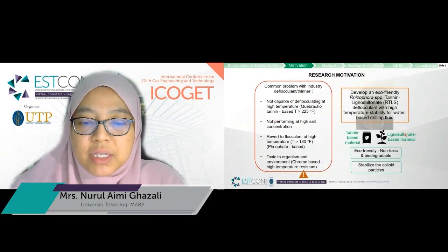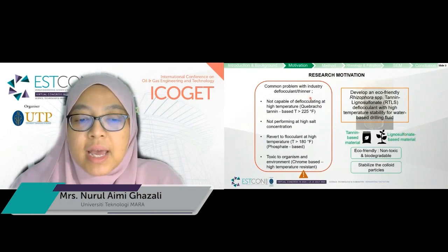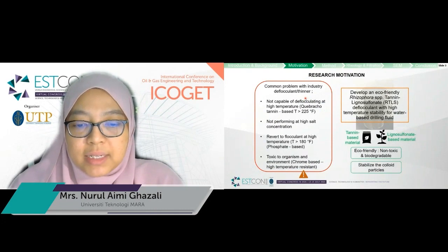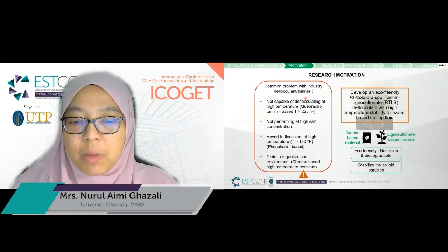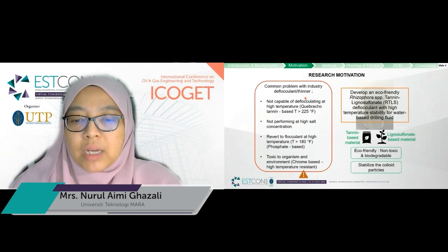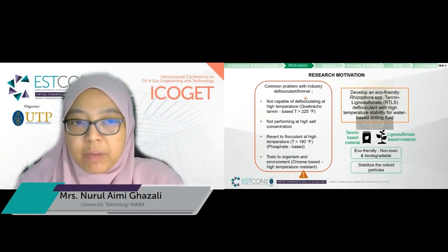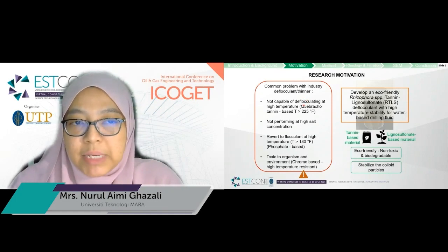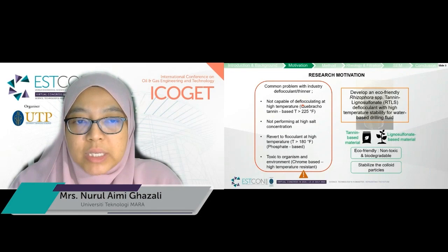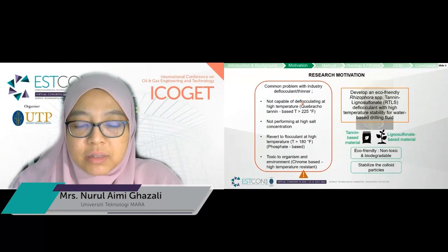In past research, lignosulfonate was introduced to replace quebracho tannin as the deflocculant, also known as a thinner. It is because the hydroxyl and ether groups have the ability to adsorb on the clay particle, while the carboxyl and sulfonic acid groups improve the technical performance and stabilize the colloid particle. The main drawback of quebracho tannin and lignosulfonate is low thermal stability. They are not able to perform at high temperature, which is more than 225 degrees Fahrenheit. They also do not perform in higher salt concentration.